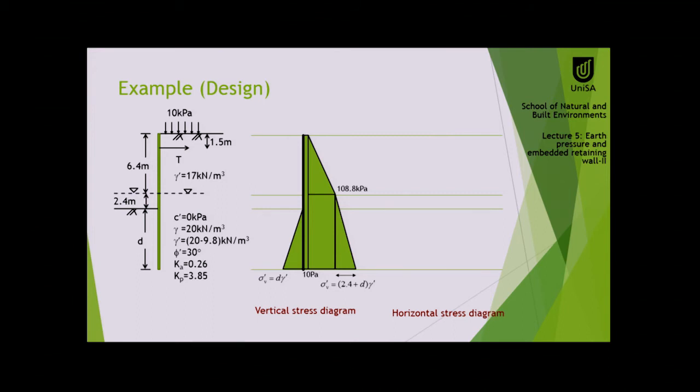Once it hits the pore water pressure, although the pore water pressure on both sides is at the same level, they cancel out, but the diagram over here, because of this reason, from 20 or 17, we take 9.8 out, that would be the slope. It would be a different slope.